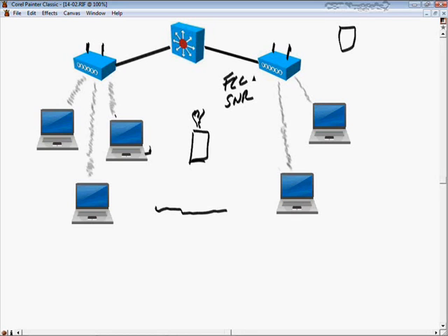Higher data rates require more bandwidth. Increased bandwidth is possible if you have higher frequencies or more complex modulation schemes. And higher frequencies have a shorter transmission range because they have higher degradation and absorption. Remember, absorption occurs when RF waves are absorbed by objects like carpeting and walls. You can get more efficient antennas to overcome that.